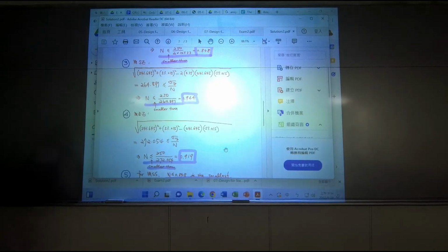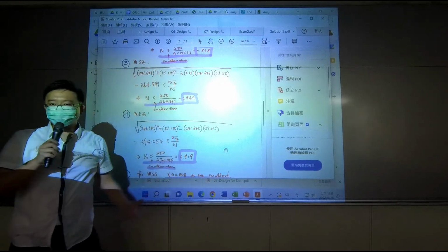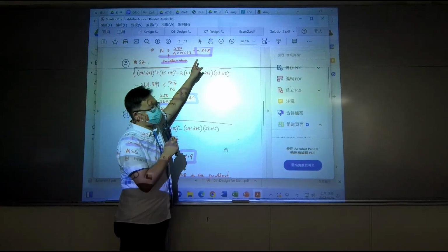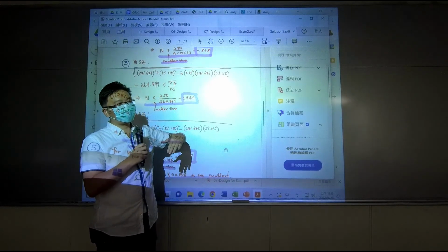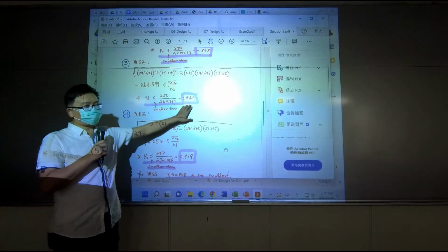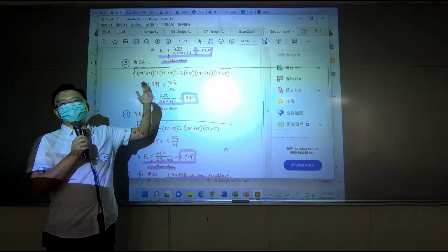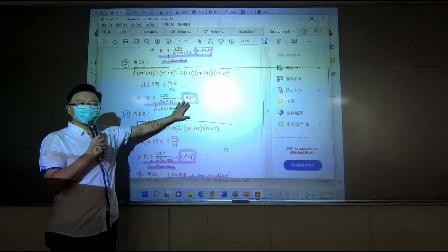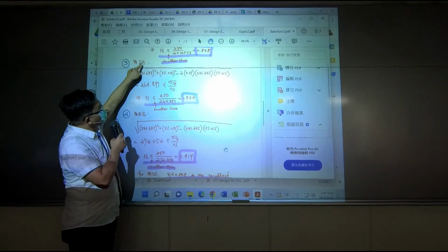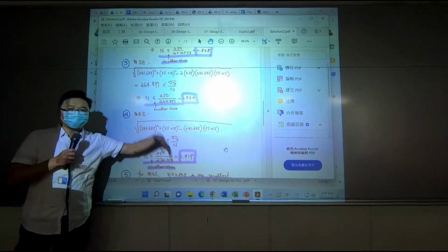Okay. So, this is the most conservative one. When we are conservative, we believe we are not safe. So, the calculated safety level is lower. We should do better. But when we use the most aggressive one, our safety level, this is like the estimated safety level, it's higher. So we are aggressive. We think we don't need to improve too much. We are close to 1. Okay, so when you use strain energy model, you're more aggressive. If you use the distortion energy model, you are in between. Okay?